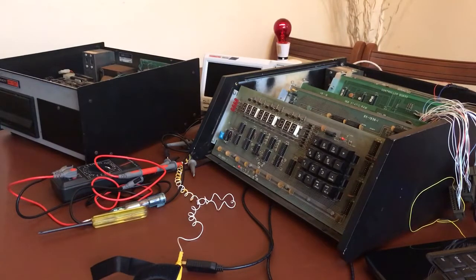I'll probably get the 4K RAM card running as well. I've ordered some chips for that because I think it's 6 of the 8 are faulty on that, although we can again do a little bit more testing now that we've got the memory testing ROM on the controller card working. And as I said, the memory on the controller card for the H17 tests okay as well, the onboard RAM, and obviously the ROM is working because it's running the ROM routines. The rails are fine on it as well, nice and stable regulators. As you can see, I've left the spaghetti dangling out in case we need to use the analyzer for any work. But now we're going to need to take a little look at where I've got with the